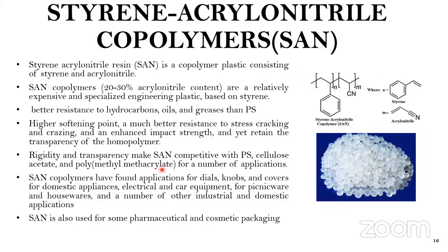For a number of applications, as compared to cellulose acetate and polymethylmethacrylate, that is PMMA, these SANs have a very high rigidity and transparency. SAN copolymers have found application for dials, knobs, or covers for domestic appliances, electrical and car equipment, picnic ware or houseware, and a number of other industrial and domestic uses.